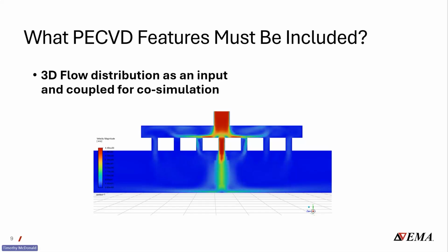These thermal asymmetries affect both neutral gas flow and plasma kinetics, feeding back into deposition uniformity. So it really needs to be a two-way coupled problem. After we've solved the computationally expensive coupled plasma and fluid flow, we need to feed that data back into a fluid solver, such as ANSYS Fluent, to capture some of these longer timescale effects.